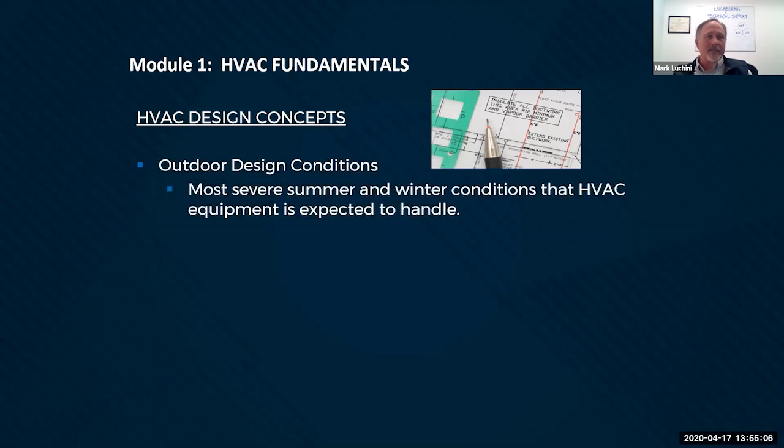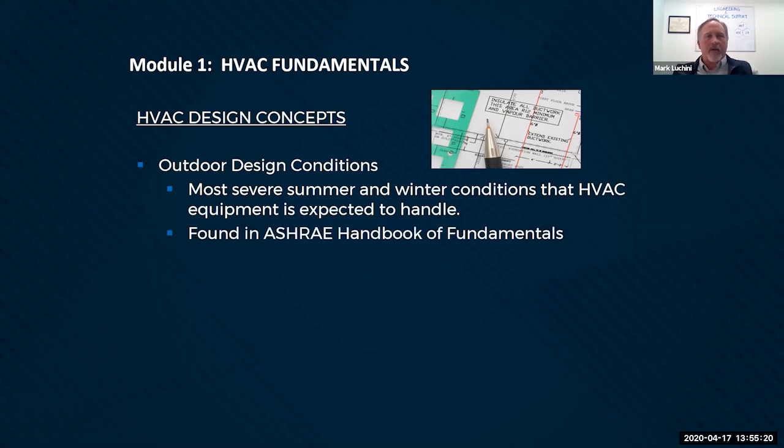Okay, HVAC design concepts. One of the first things the engineer is going to take into account is, what are my outdoor air conditions? I need to figure out what are the worst conditions my systems are going to have to deal with. You find those, they're all tabulated. Somebody's already done the homework. Good old ASHRAE Fundamentals Handbook. You get one of these every 4 years from ASHRAE. I got more than I care to admit. But that's like the Bible, that thing.